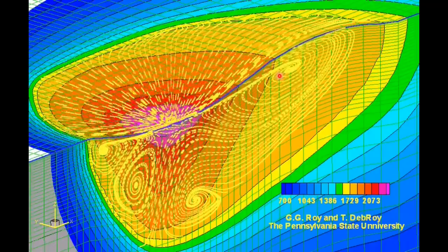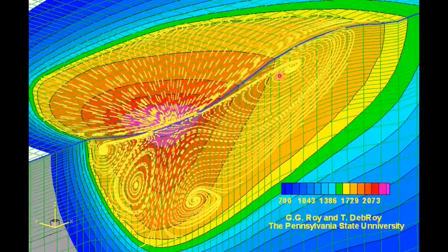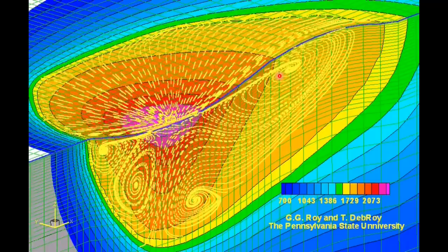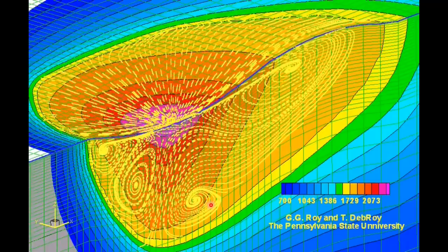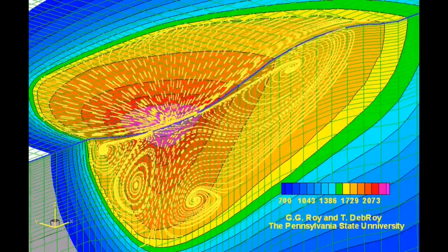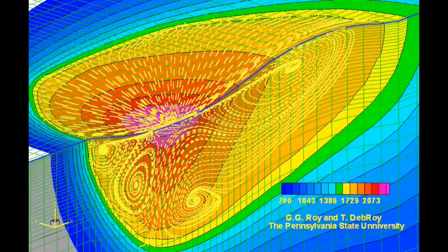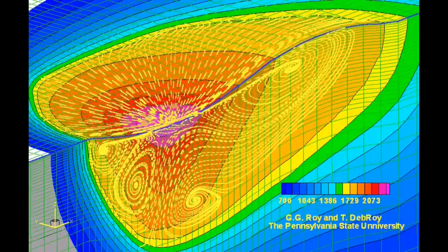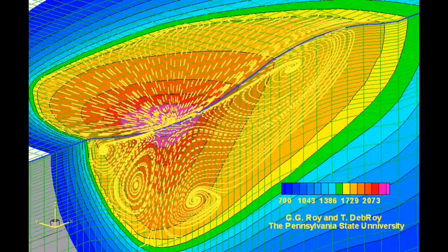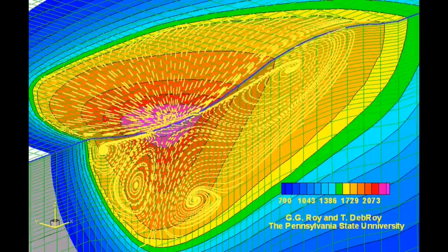They form because of the spatial gradient of interfacial tension, which is a stress. And also there are two loops down below. And these patterns are happening because of the electromagnetic force field that is driving the flow. So there is a temperature field established and a velocity field established during additive manufacturing.